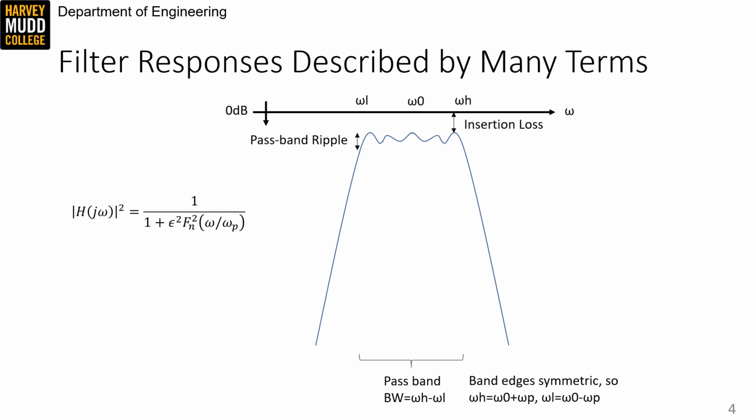There's some loss in the passband, which is referred to as the insertion loss. The transfer function also varies in the passband, and that behavior is referred to as passband ripple. The passband ripple measurement is the difference between the insertion loss and the lowest allowed value in the passband. Some filters have passbands that only ever decrease, which means we can use the vocabulary word monotonic to describe them. Those filters don't have ripple in the sense you might think of it, but we still call the steady decay of the transfer function ripple.